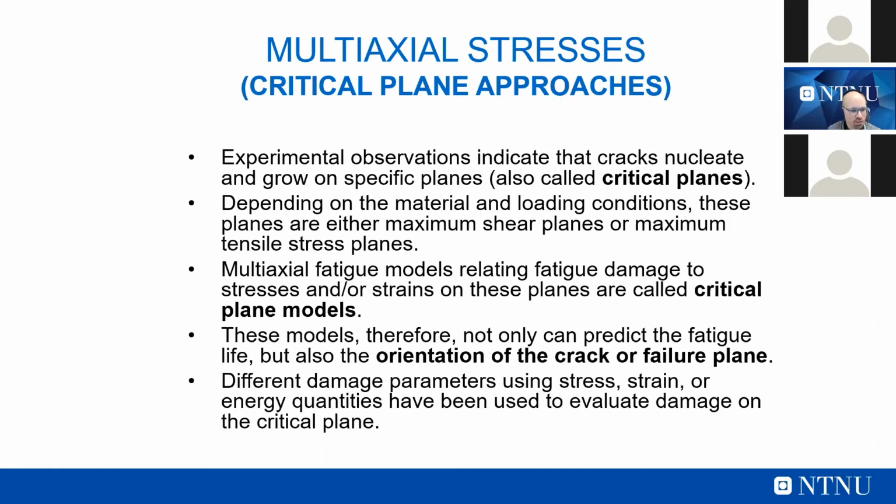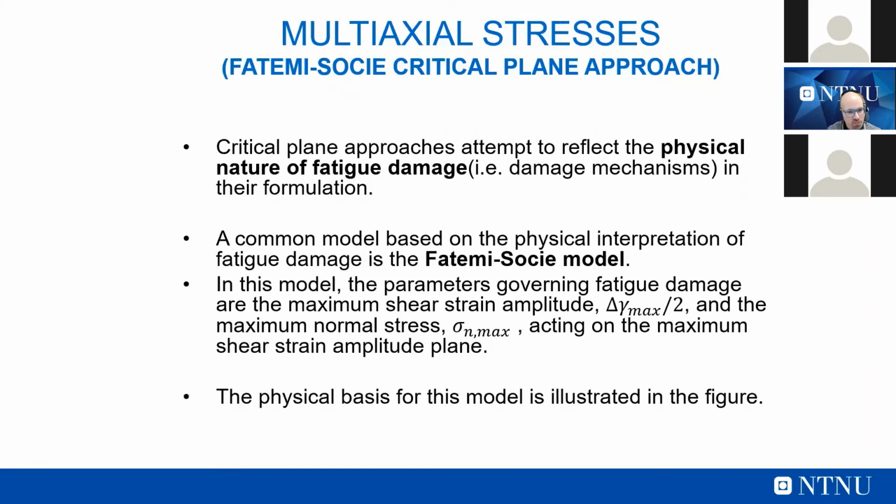And I want here to introduce only the most significant approach, I would say, that is due to Fatemi-Socie. It is not the only one applied for multi-axial stresses, but it is of course the most cited. You can find many references on it, so it is trustable, and you can find a lot of work done using this method. The idea of this method is that it is a critical plane approach that attempts to reflect the physical nature of fatigue damage, and it is called the Fatemi-Socie model. Now we will discuss a bit the parameters inside the model. The parameters are very simple, and the parameters governing the fatigue damage are the maximum shear strain amplitude and the maximum normal stress acting on the maximum shear strain amplitude plane.